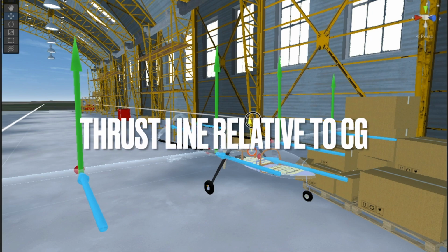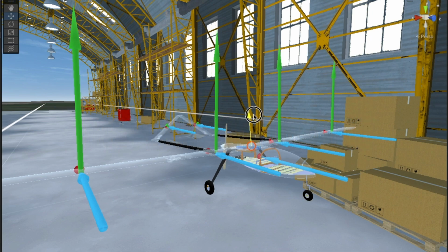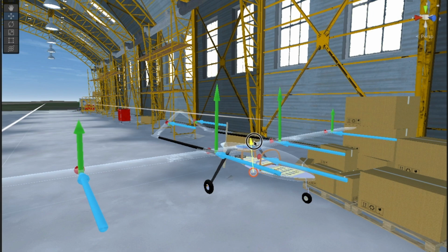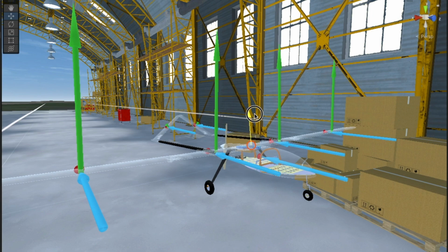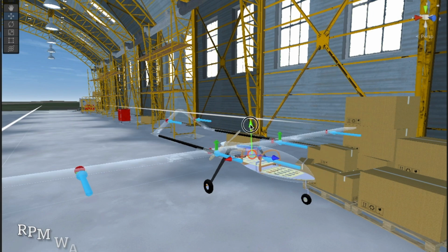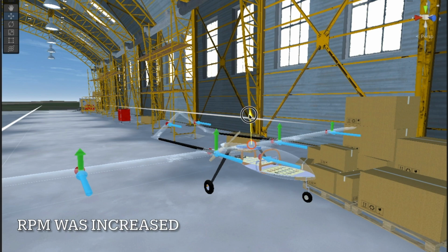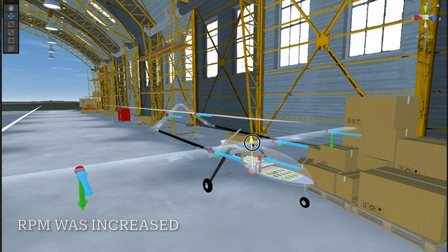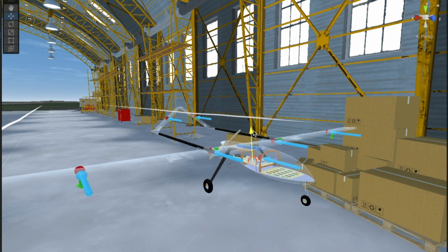During the test varying a range of CG vertical positions, it was observed that increasing the vertical displacement of the CG increases the magnitude of the nose-up pitching moment. It was also observed that increasing thrust amplifies these effects, further intensifying the pitching moments associated with changes in vertical CG position.